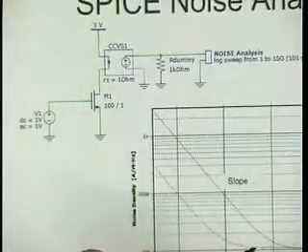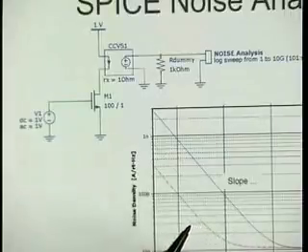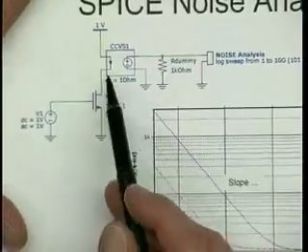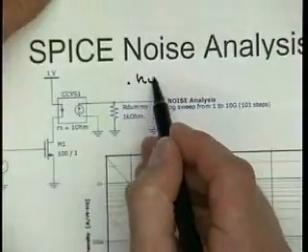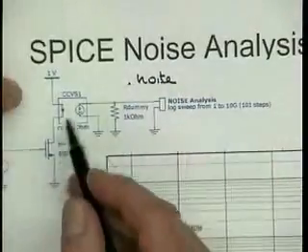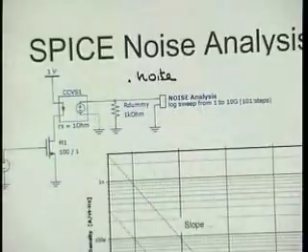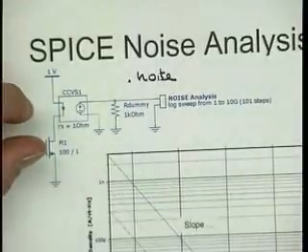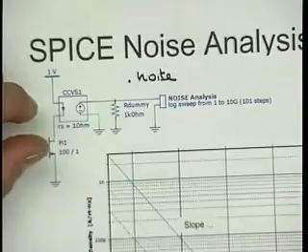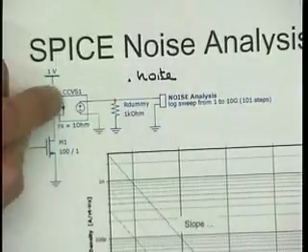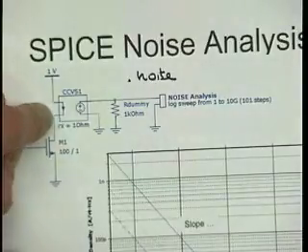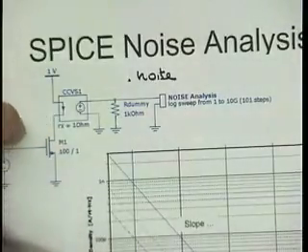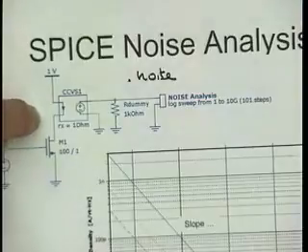I do this simply because our equations immediately specify what the noise current is, and then SPICE has a statement called dot noise. You have to specify at what node you want to measure the noise. In many versions of SPICE, there is no dot noise that measures noise current. There is only one for voltage. So in this case, where we want to really know the noise current coming out of here, is it for you also not sharp, the image? It's not in focus. Or is it my eyes?